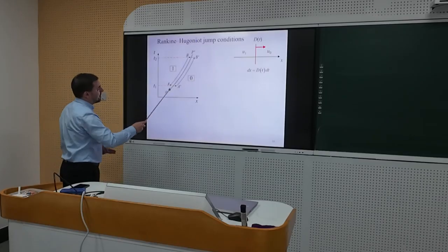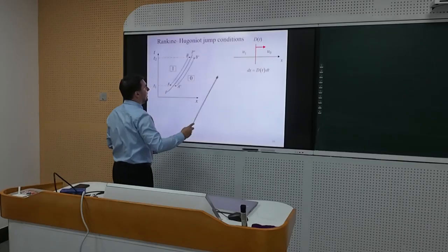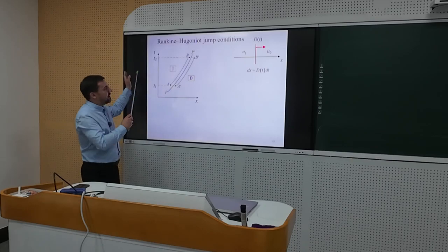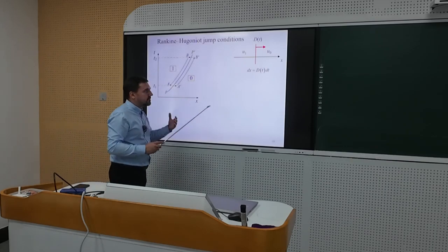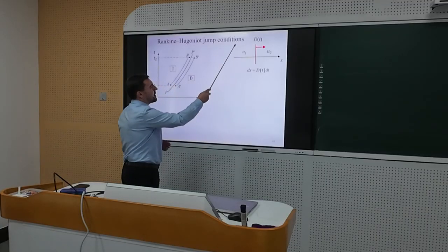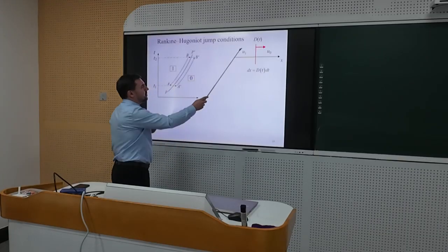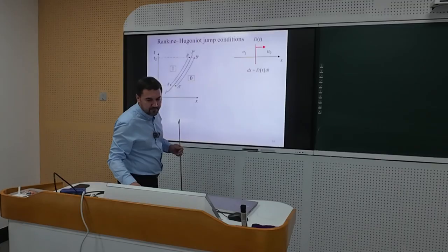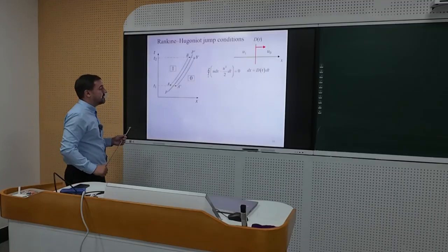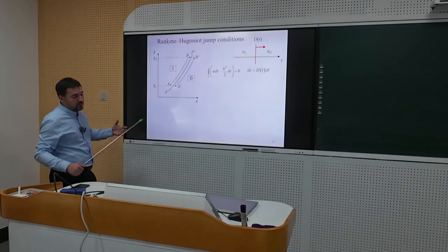So 0 means the parameters here. Actually, this is just u sub 0. In gas dynamics, it will be rho, u, and p sub 0. And here, the parameters behind the shock wave. So the goal is how to find the parameters. In gas dynamics, the goal is how to find parameters behind the shock wave if we know the speed d. But actually, here the goal is how to find this velocity d. And as we discussed, we should work with this integral form of our Hopf equation, because we want to find the weak solution.